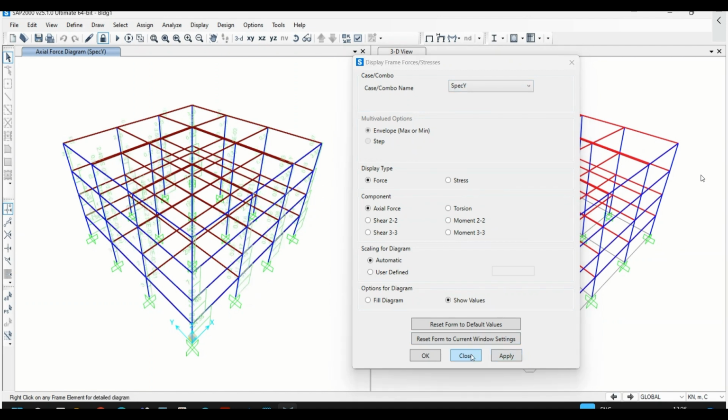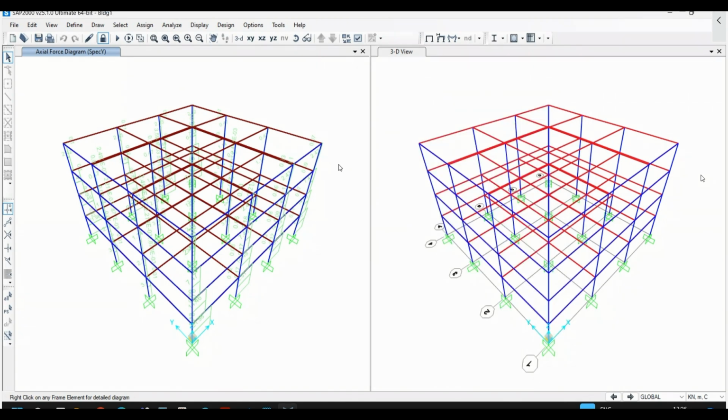To deal with this, both ETABS and SAP2000 are capable of dealing with these spectrum results in the design. It will create 8 sub-combinations, changing the signs, permutations. For example, for a column there will be P, M2 and M3 biaxial moments. So the signs will be changed in 8 permutations, and then the maximum obtained from that will be used in the design. That is taken care of automatically by the program.